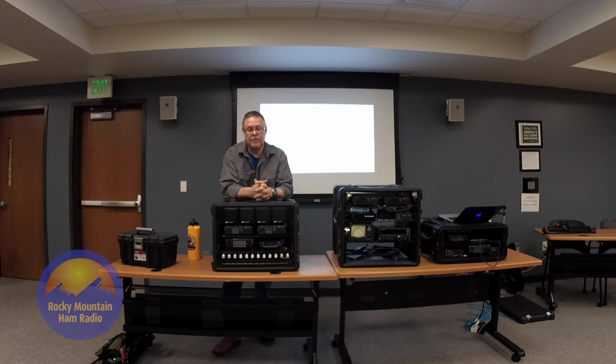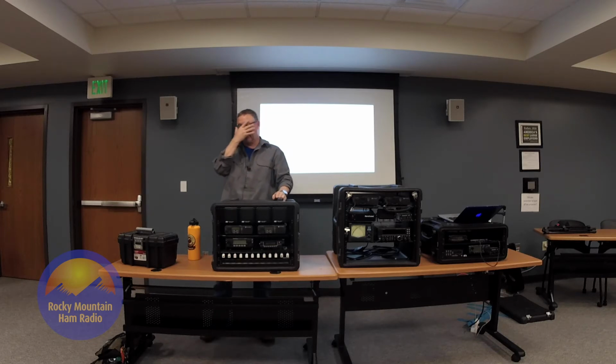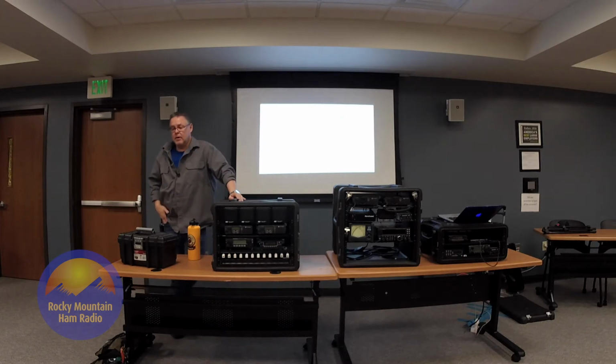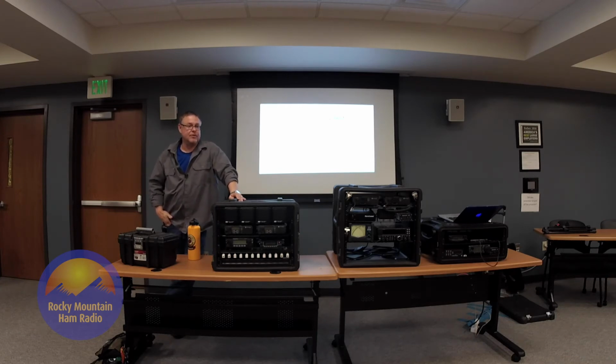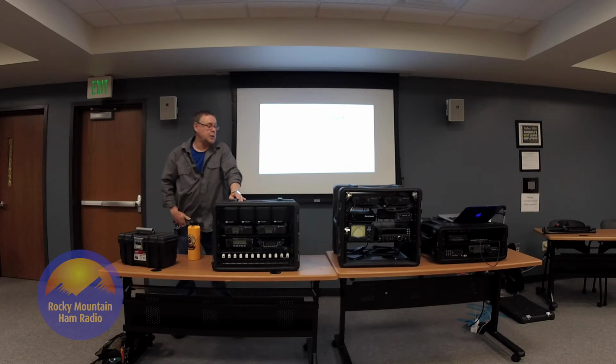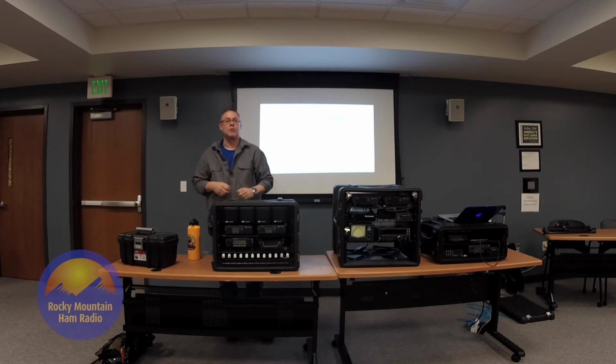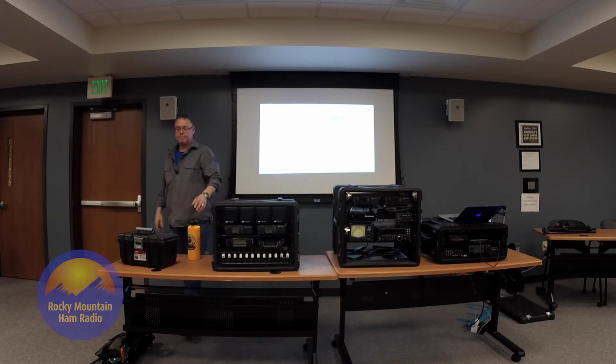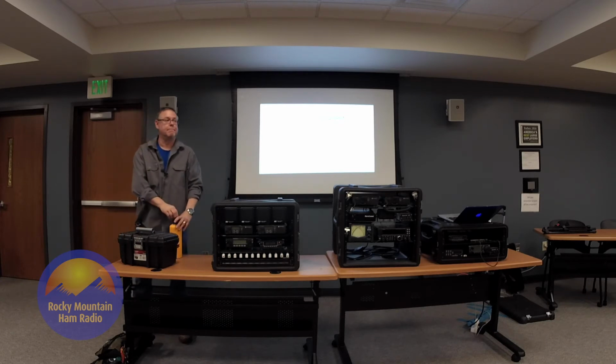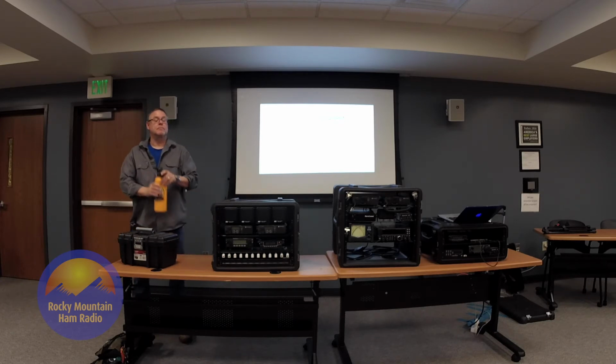A standard magnetic or a non-sine wave inverter can damage some radios. Most of them are protected now from it, but there was a time. There's equipment out there that does not deal well with modified. Yeah, if you have a Weller soldering iron, the big gun ones, I'll tell you from experience, a non-pure sine wave will burn it out in a second. It'll smoke it. So, yeah, I smoked mine. Make sure you test your equipment before you take it out, because you don't know how it's going to be. It's very unpredictable.